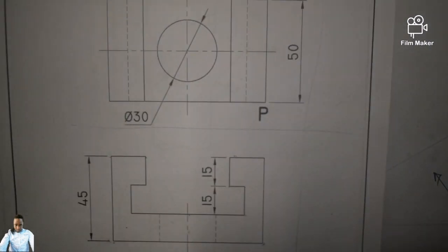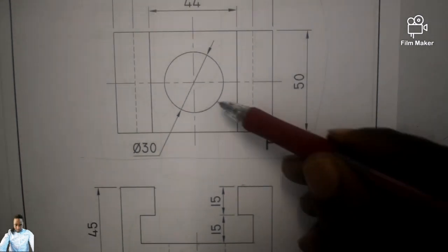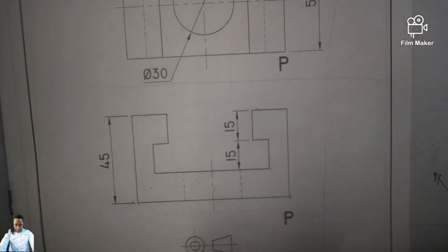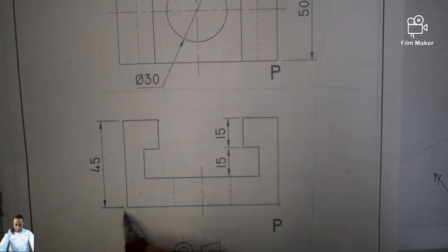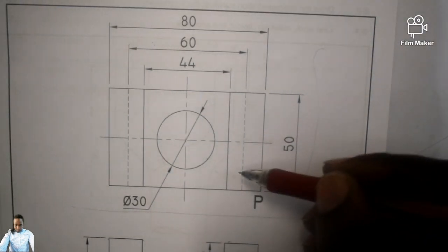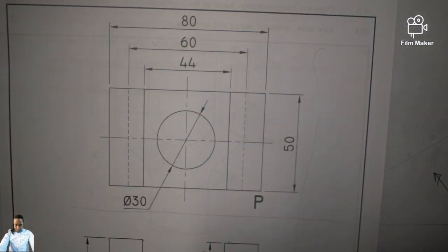So we know that the front view and the top view will always share the same length. The front view and the right view will always share the same height. And the top view as well as the right view will always share the same breadth or width, whatever you might call it. Now, why am I saying that? Because I'm looking for a dimension from here till there. It seems to be missing. So I'll just come up there and read it from the top view.